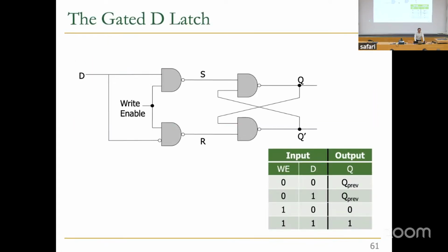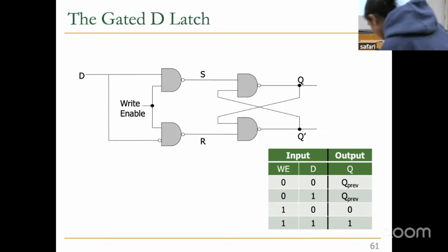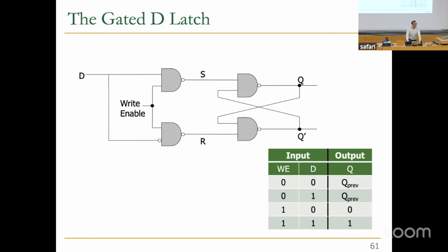So now we know how to build something that doesn't violate any logical principle and also doesn't have a metastable state, which you will learn about in the timing lecture. But you see that we had to use 1, 2, 3, 4 NAND gates for it. And you remember from the past, a NAND gate is 4 transistors, right? So that's 16 transistors for you. Not cheap. Just to give you an idea, a DRAM cell stores 1 bit using 1 transistor and 1 capacitor, much smaller.